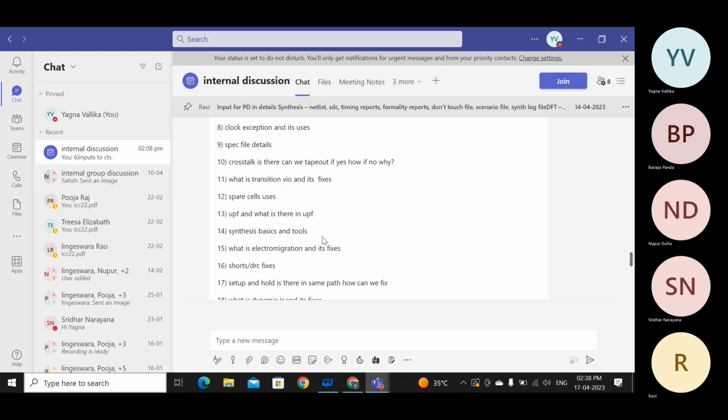After that 0.6 value, if it's 0.7, the characterization table is not available for you. Do you understand? When the delay calculation happens, it does not know what the transition for 0.7 is. There is no value for it to actually work with. What would be the delay? So it will do something called extrapolation. You should already have studied mathematics, interpolation and extrapolation. Interpolation is good.